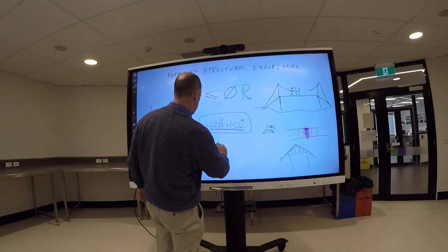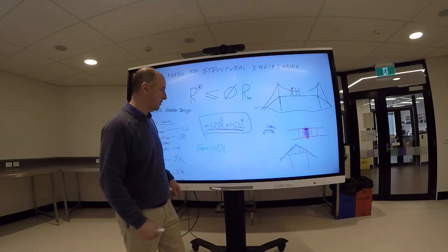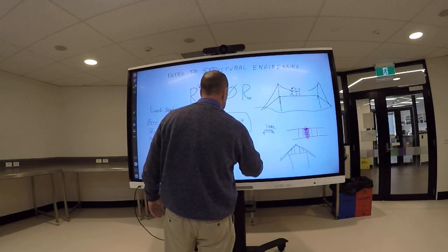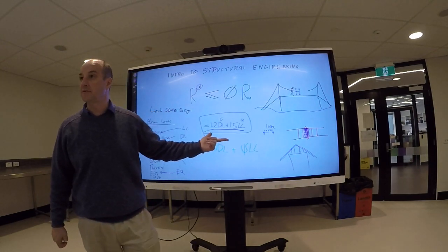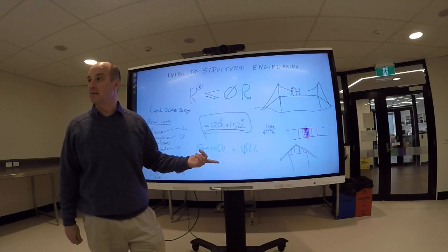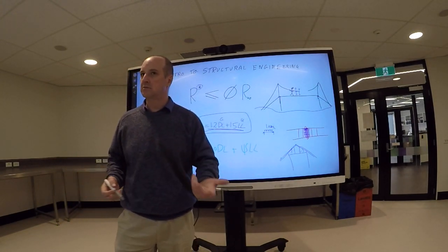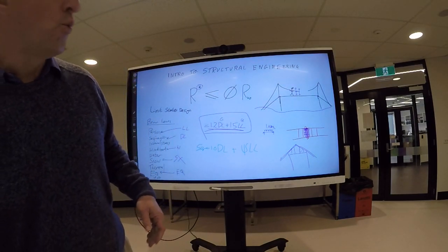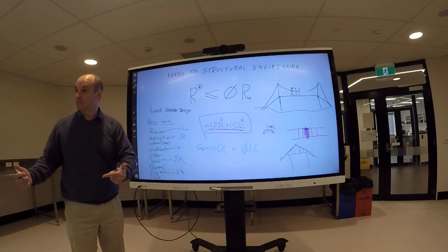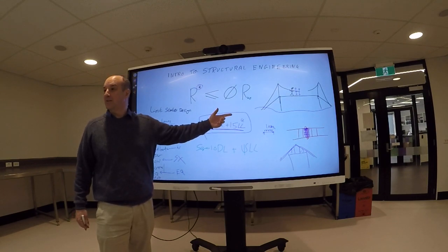In fact, for serviceability, we normally take 1.0 times the dead load, exactly the dead load, plus, and here's another funny Greek letter, a portion of the live load. We don't even often use the full live load because the full live load is a pretty rare thing, okay? Depending what sort of live load it is, depending what the structure is. And that's all in this book as well. And when you're adding wind into it, sometimes you don't use the full live load in the wind, okay?